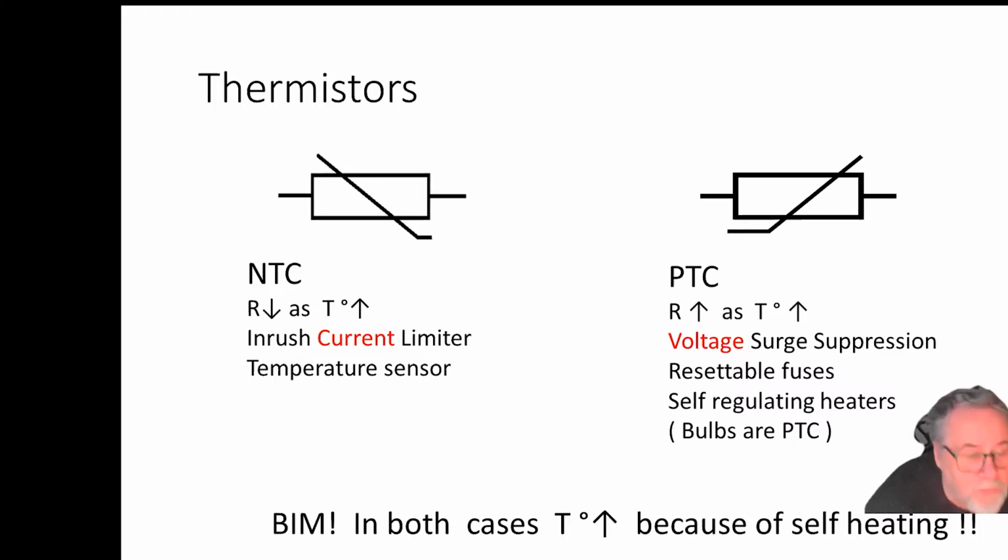The real problem, though, is that thermistors are actually rubbish at measuring temperature, because as a thermistor measures temperature, it draws current. And as it draws current, it gets hot. And as it gets hot, it measures a different temperature, and its current changes and it measures a different temperature. So actually getting a thermistor to measure temperature is really quite the trick.